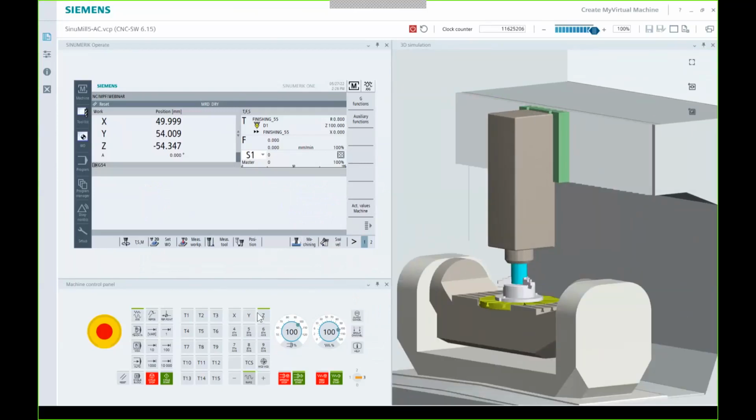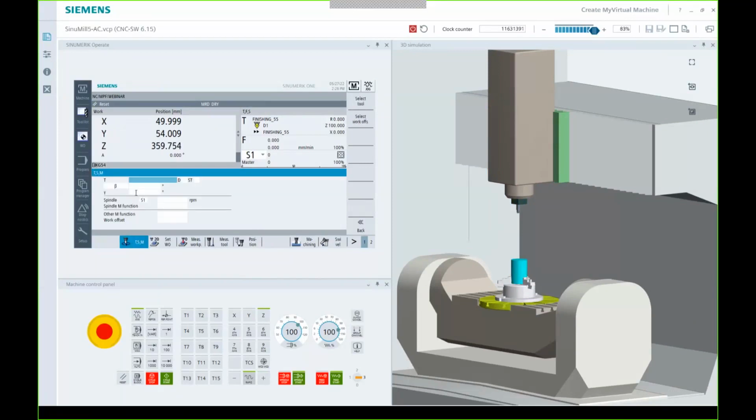Is this up? Z up and out of that part. So right now, I have no tool carrier active and there is no rotation around my X. So if I just come in here to TSM and I tell it beta axis 45, cycle start. Oh, Y0, my bad. Didn't get the gamma.